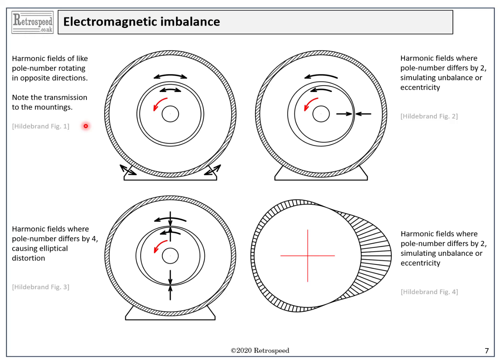Of course, it vanishes if the motor is operated as a balanced two-phase motor, but this condition is extremely rare. The problem with this oscillatory torque is that it is transmitted directly to the mountings, which provide a path for the transmission of noise. For this reason, single-phase motors are often provided with compliant or resilient bearing mountings, springs, to attenuate the transmitted torque oscillation.